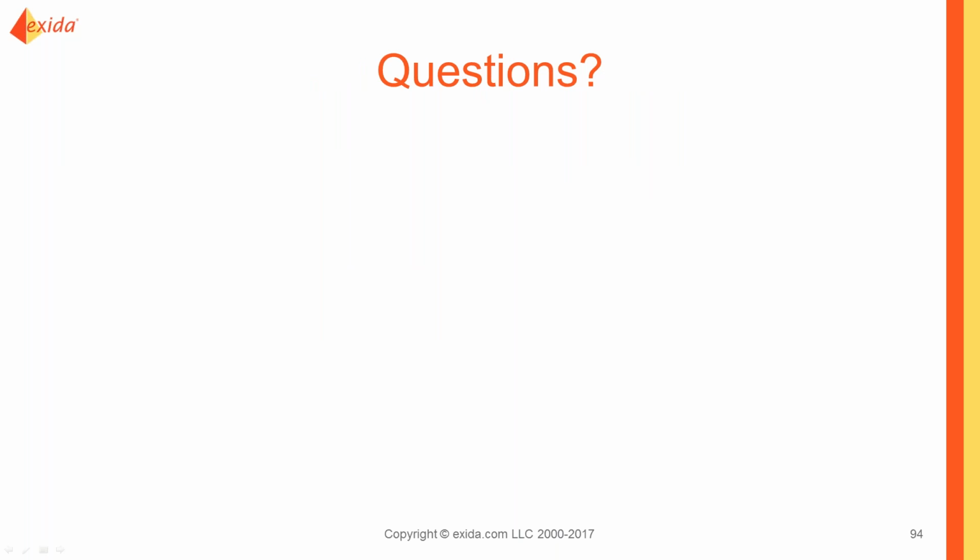So let's see. So here's one: how would you specify SIL or performance level for an e-stop, a complementary protective measure? So in Europe, there's a requirement, and what we're seeing is that that's typically specified as a SIL 2 function. Not specifically, but there are requirements for the reliability and the effectiveness from some EN standards for a push button.